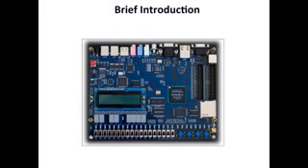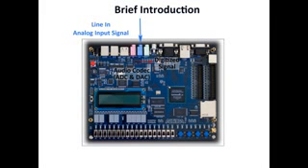The first experiment is to create an audio loopback application by using the DE2 onboard audio codec. The audio loopback application will convert the analog input signal and pass digital samples from the ADC directly to the DAC as analog output signal without any processing. The second experiment is to investigate the quantization effect of digital samples introduced by digital sampling.